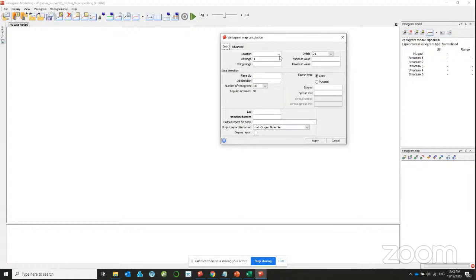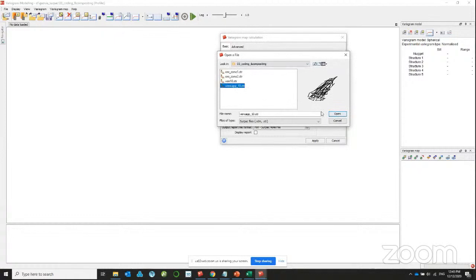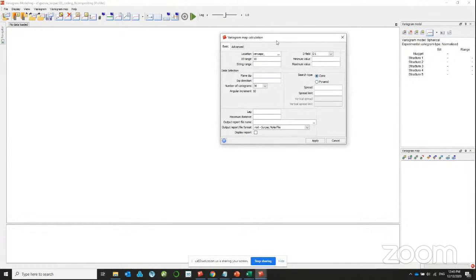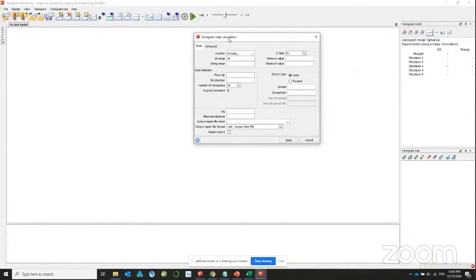You will just get your database file for the samples, and you define the field that contains the grades. You need to define the azimuth and dip to start with. So you just make it 0, 0 to start. And then you need to define the number of variograms with an increment of 10.